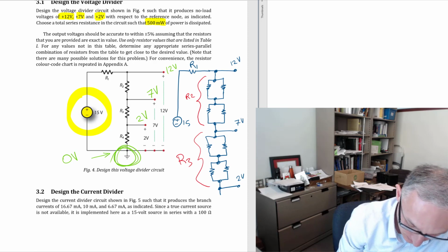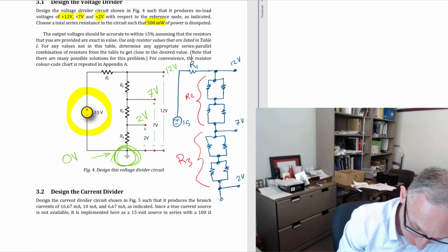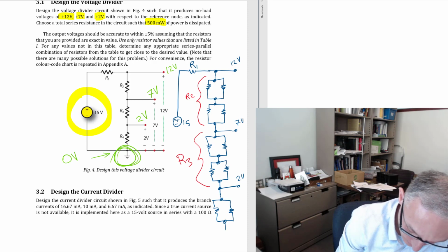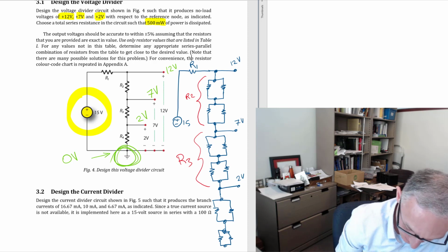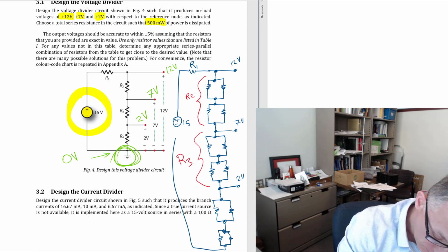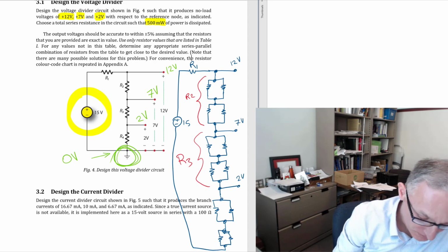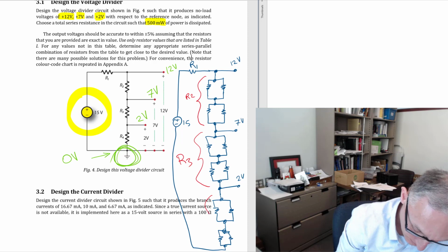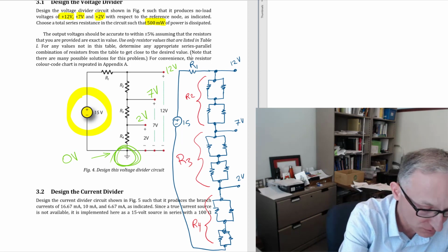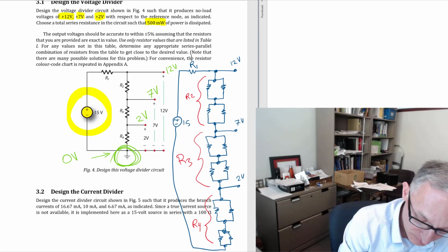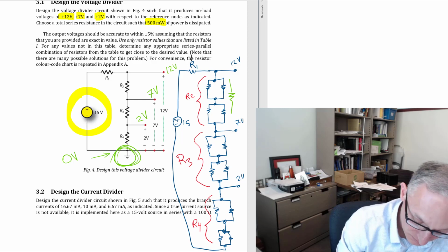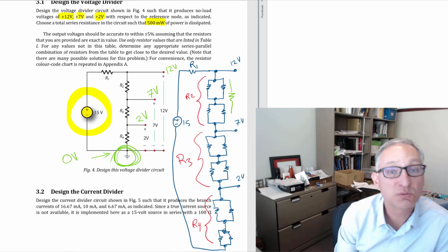And then at the very bottom here, we'll have that final resistor that you're going to have to design. And it could look like this. Who knows, maybe there's going to be 3 parallel resistors, if that's what makes sense in your circuit. And this is the last resistor, and that's the one that's going to come around and go back to the negative. So that last one is going to be the R4 resistor. Now each of those, you don't know. Maybe this is just one resistor, or maybe it's 2 parallel resistors, whatever it is.